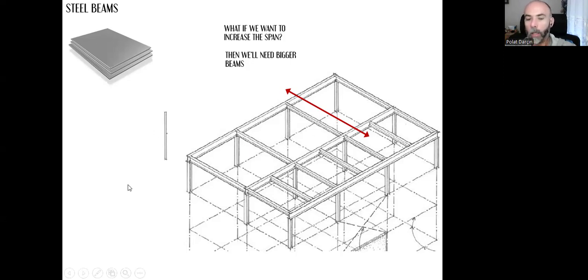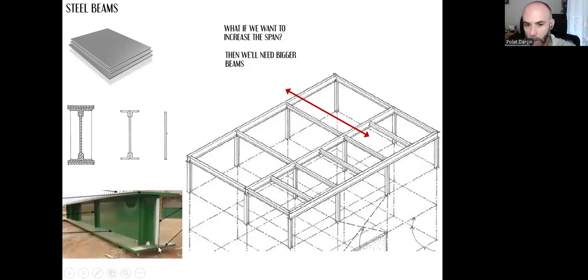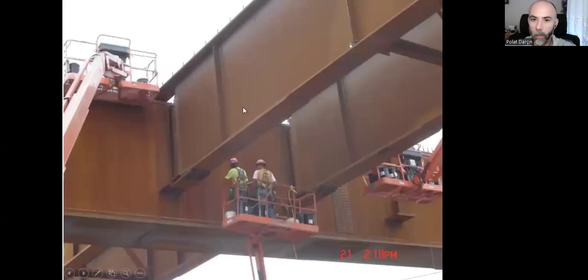Like I can get a long, thick sheet, and I can have these L-shaped little profiles and connect them with horizontal bigger sheets, something like this. As you can see, I have a very large beam, but it's lighter than the ready profile. So I can use them to create larger structures, bigger spans.